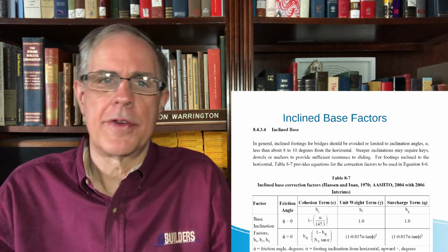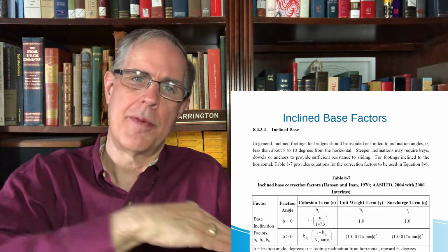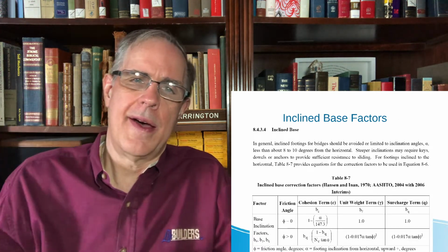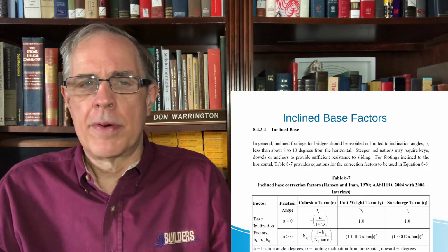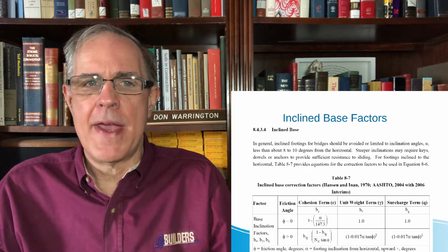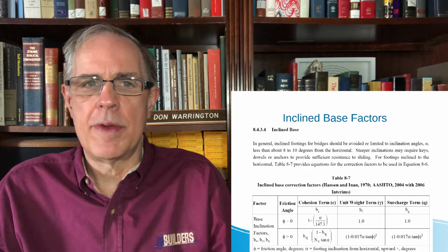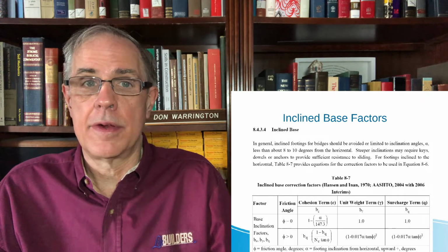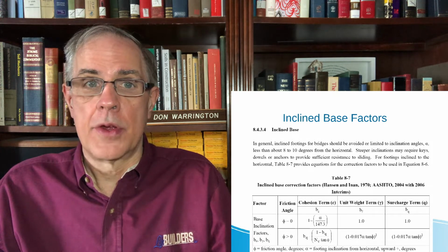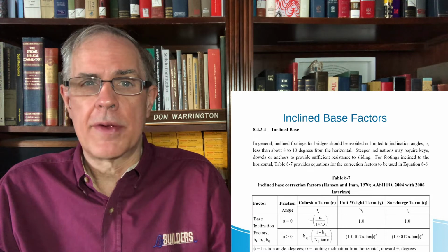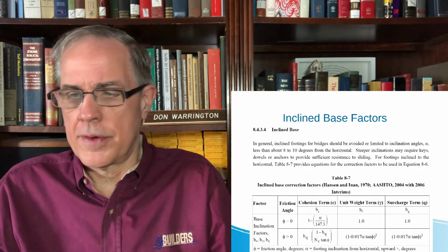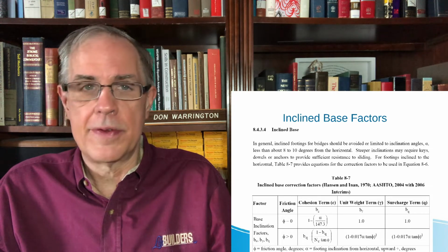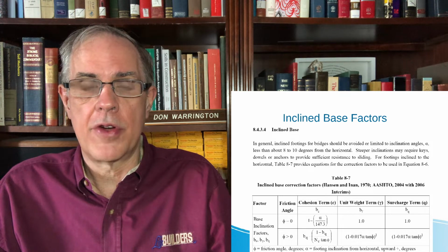Inclined base factors are in case they slope it this way. The problem with inclined bases, they have been used, is they're a little tricky to build, particularly in cohesionless soils. I'm not going to spend a lot of time there. I'm just going to warn you of the existence of inclined base factors. There are other ways.